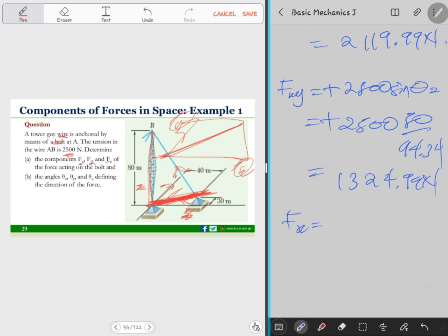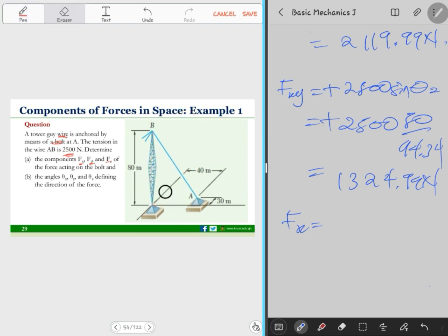In order to get this Fx, now let's look at direction. It is very important, because if you miss the direction, you are doing something else. When we started, we did it this way, where we have our X here, Z here, and here's our Y. And now we have the Fxy. We know the Fxy was actually here and the direction was this way. Because it's in the opposite direction, the X component here will be negative, right?